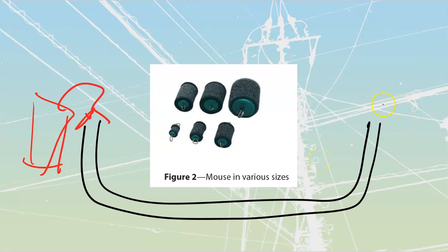And then what you're going to do is have a bucket of twine, and then you're going to have a plastic bag. Most people just inflate a sandwich bag or something like that. You can also take that white foam that they place underneath the sill plates at job sites. You'll find throwaway sections of that. If you roll that stuff up into a nice light little thing, a bit smaller than the size of your conduit, that stuff pulls through really nice as well. But you're going to have something attached to a string, and then you're just going to insert that in there, and the suction is going to pull that through.